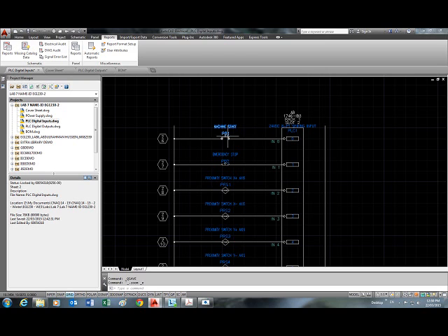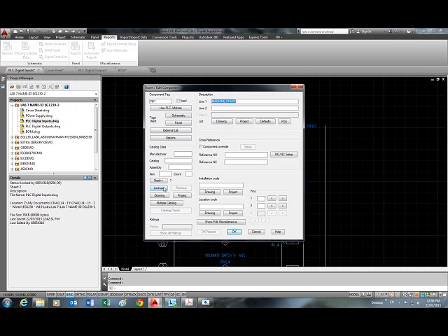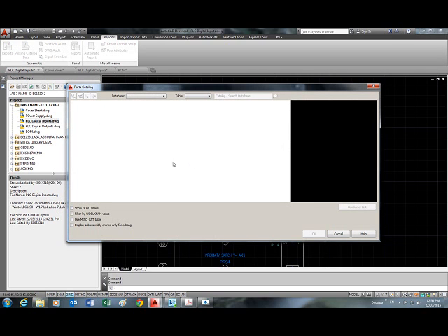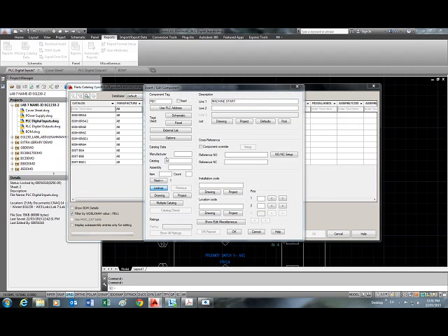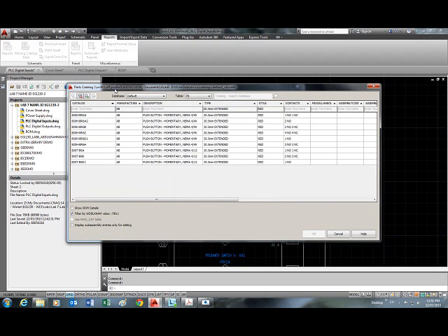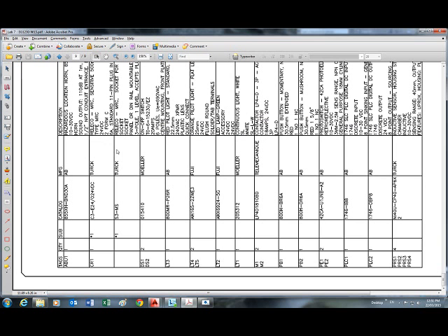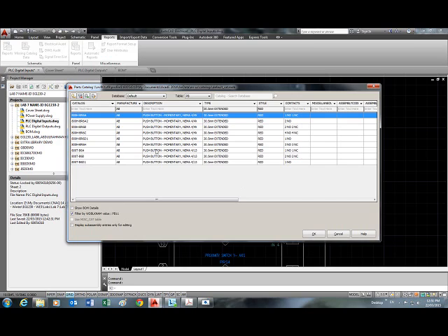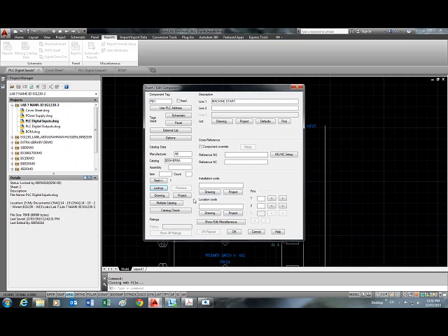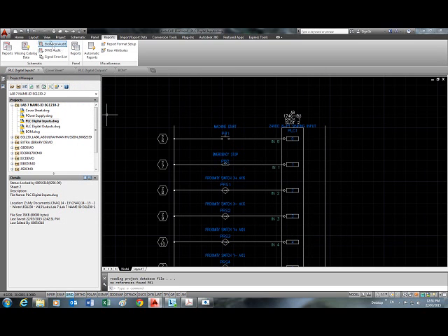BR6A. So we can go right click, edit component, lookup, be patient with the catalog, and again always remember to save. So there's BR6A 800H, and we'll say OK, and there it is, OK, and save. And you continue to do the same for the other components.